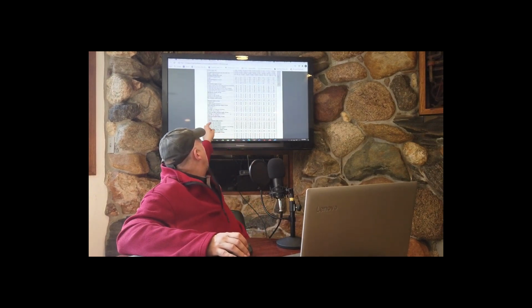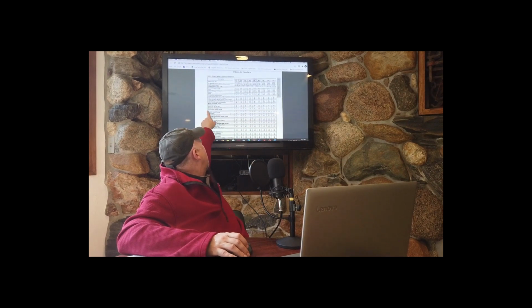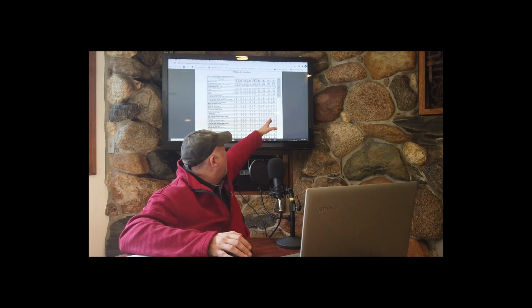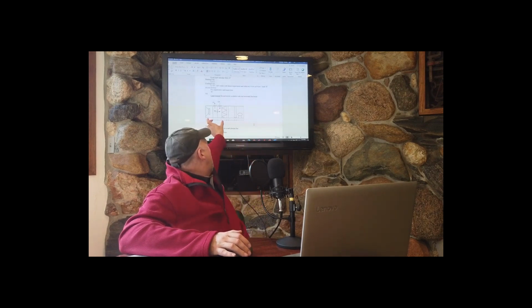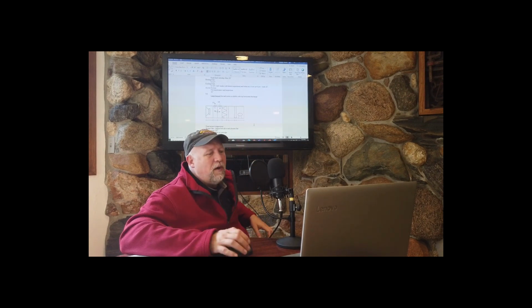All right, back to the next piece of this. What other items are we going to have in here? Well, let's look at the economizer. There's only one line. There's no options here. The economizer for a 40,000 CFM air handler is 112 inches long. So back on this, we'd have this economizer section be 112 inches.